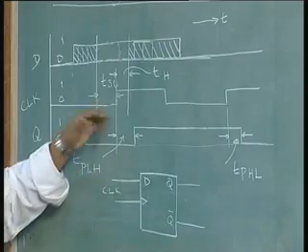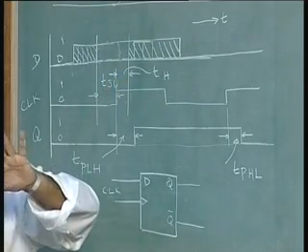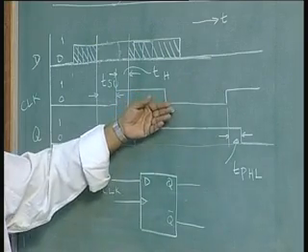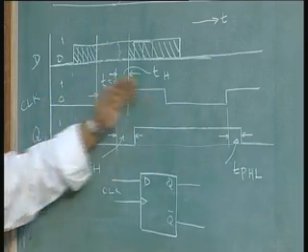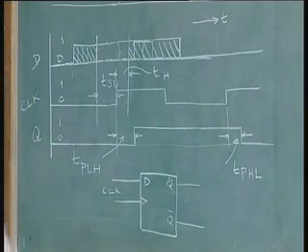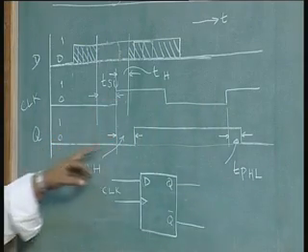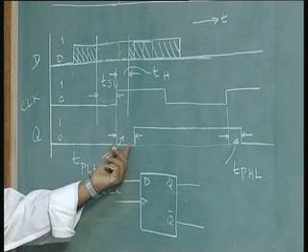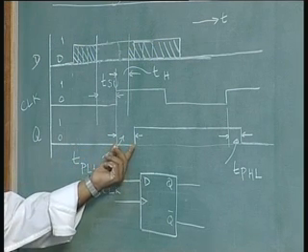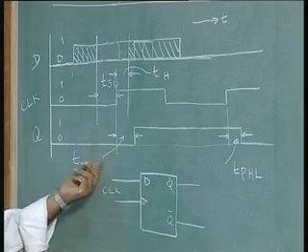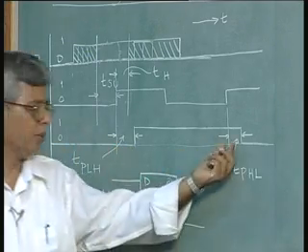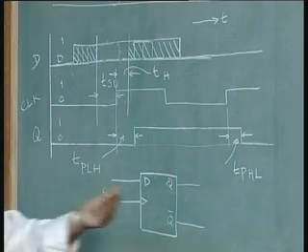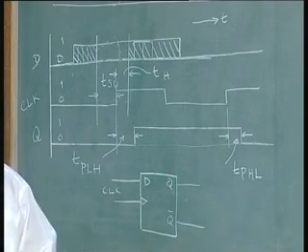So, that is what I am trying to say. You will have to know all these things. The 5 things are involved. One is the clock period, the maximum clock frequency, which is implicitly told; I have just assumed a clock waveform. And then there is this Q changing. There are 2 periods. One is called the propagation delay because of the transition from low to high. Another is called propagation delay because of high to low. The average of the 2 is a typical value. The maximum of the 2 is used for worst case designs.